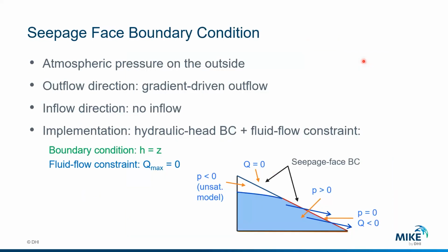There are some special boundary conditions available with this unsaturated problem. The most common is called the seepage face boundary condition, and it is something that I am going to use. It is used to estimate, as the name says, seepages. There is a second boundary, for which I don't have slides here, called free drainage, which is used for simulating outflow conditions from the bottom of your model in case the water table is far away from the end of your model domain.